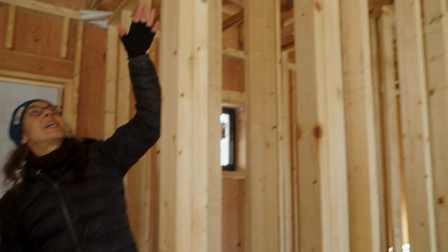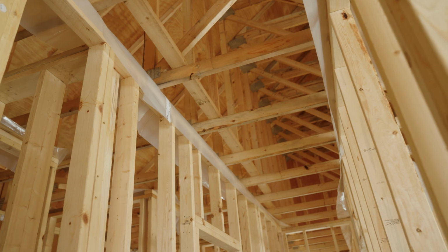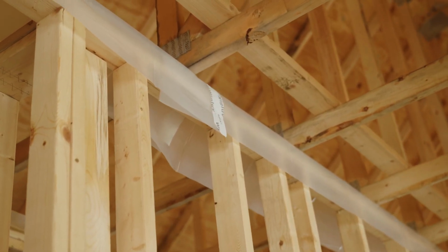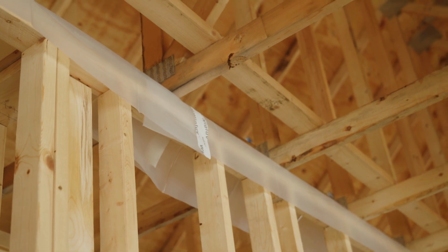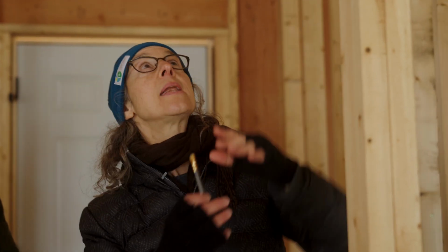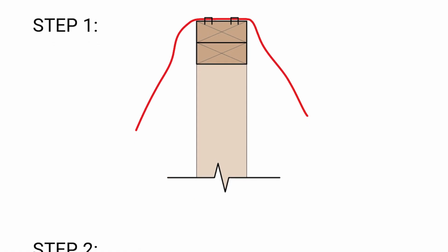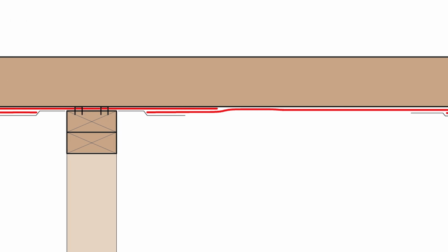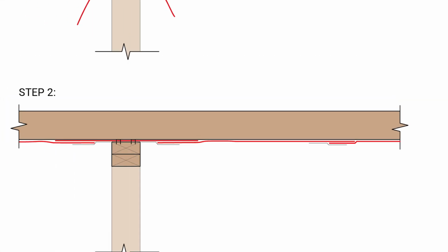Putting about an 18-inch wide strip of poly draped across or just tacked in place over the top of that partition wall as you're putting it into place means that you will have the continuity of the air barrier at that ceiling plane. And later, when it comes time to put the rest of the polyethylene up in place, you have a straight shot at sealing that joint with tape, instead of the other way that I've seen.